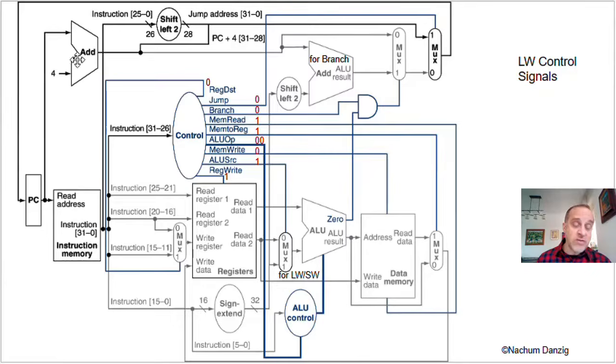That's called the instruction fetch stage. We've read the instruction, we've fetched the instruction, and we've also incremented the PC. The next stage is that the controller actually gets the command and starts to think about it. In the second stage, it's already producing the values which will be used in the third stage. Also, the register file is reading in these registers and producing output on these lines.